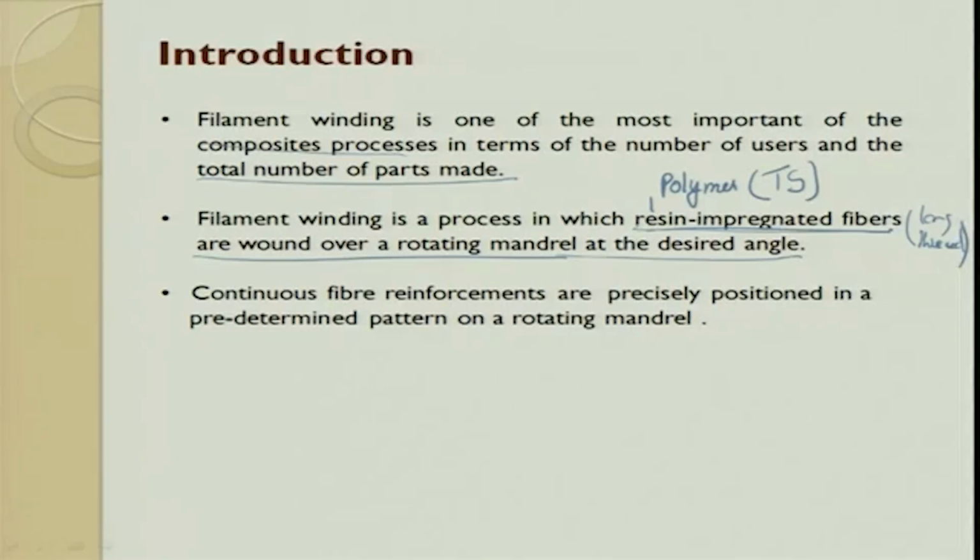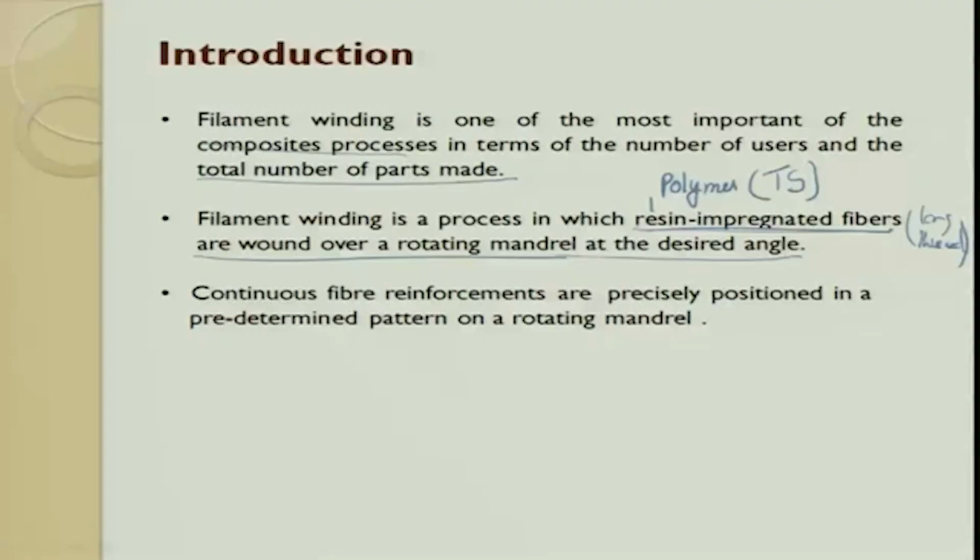So, the basic form is going to be a liquid. The fiber is going to dip through it and go, and keep in mind, the fiber which is getting coated with resin is already given a silane coating such that you enhance the wettability. That means you have a very good interface between the glass fiber and the resin.